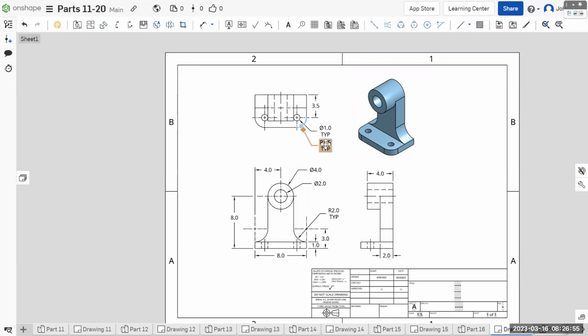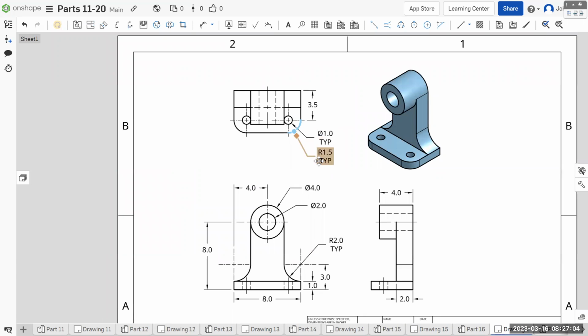How would you make this? Well, you'd start with a base that's a rectangle that's 8 by 3.5 plus 1.5. Okay. Then you'd round over these edges, which are 1.5 inch radius. Then you'd extrude it 1.